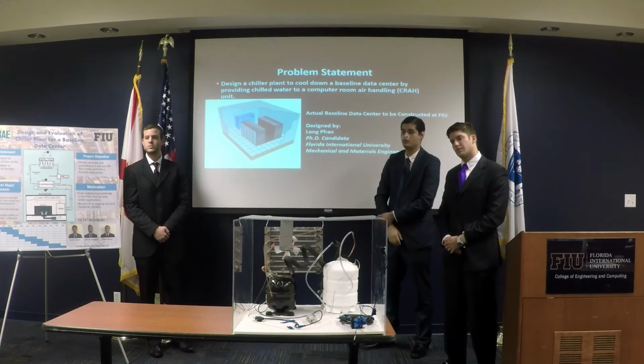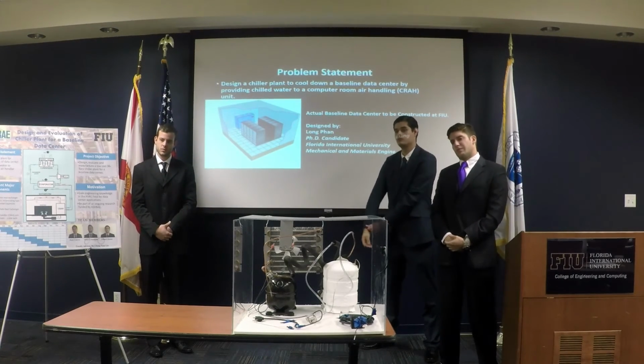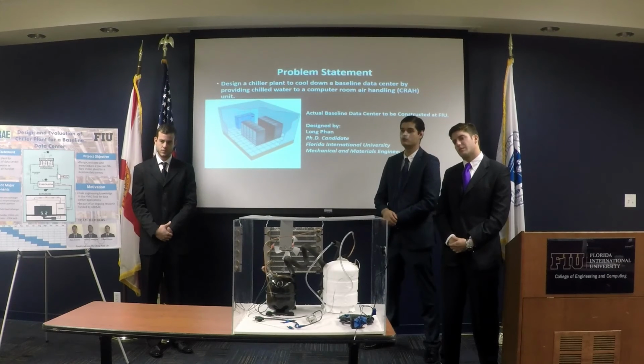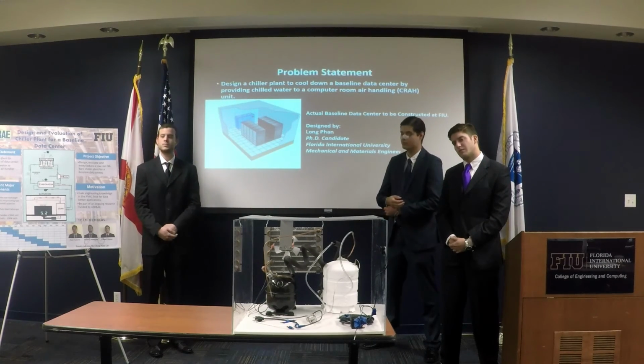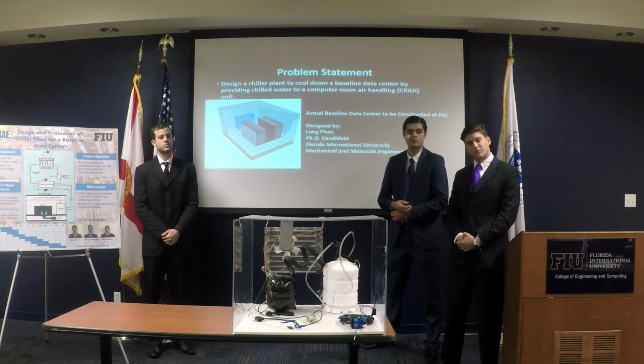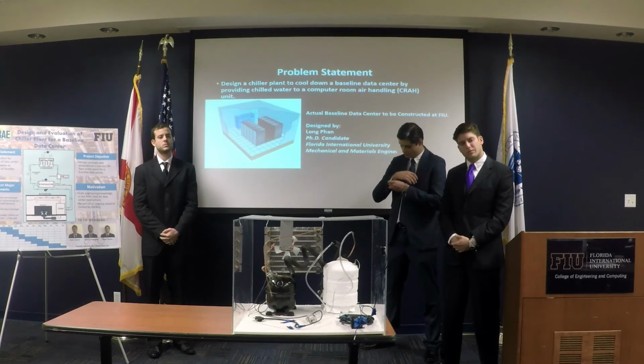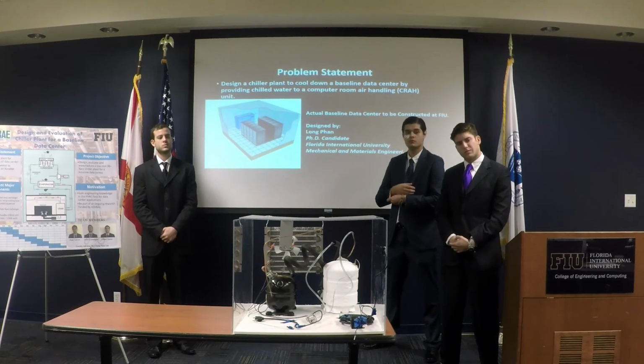Okay, because I have a building and I have 40 machines in it, and on a cold day in Florida, after we turn them on in the morning, an hour or two later, the place is warm. So the calculation is based on the size of the building, how much I have to air condition, how many machines I have in it. Well, in this case also it depends on what equipment's in there, because if you've got blade servers, they produce more heat than just a 1U rack or 2U server.